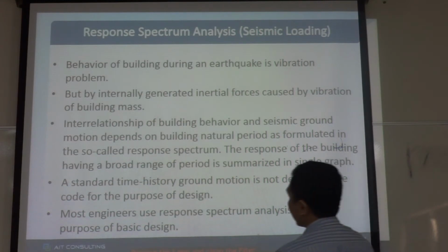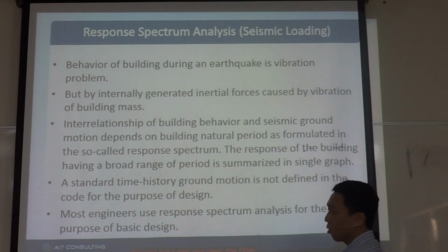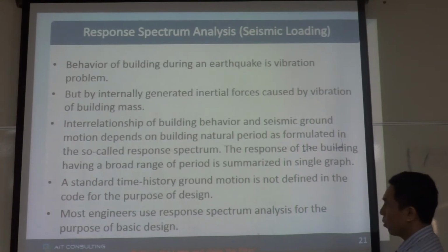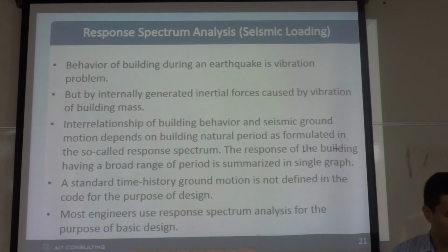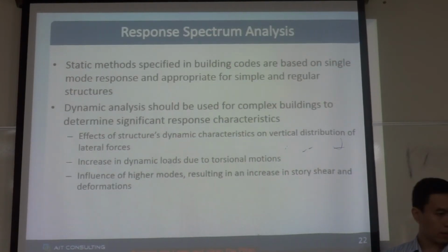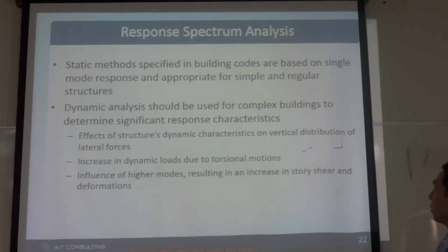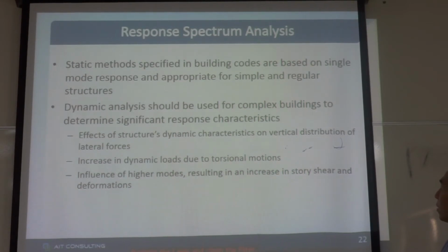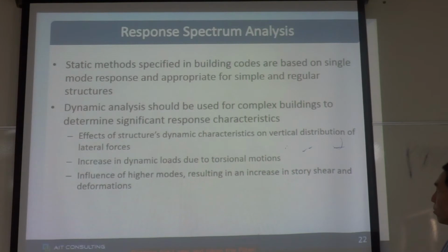Normally, we do not run the time history analysis in code-based design. Most of the engineers use the response spectrum analysis in basic design. But for static methods, we use them only for very simple and regular structures. Mostly we use the response spectrum analysis.